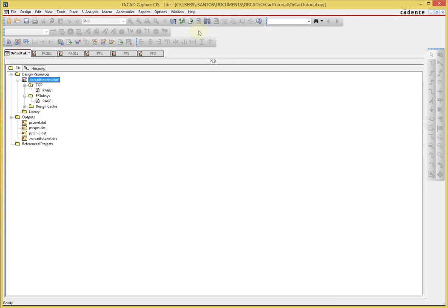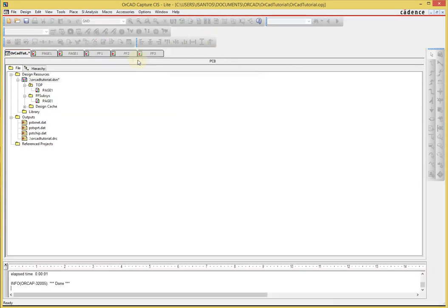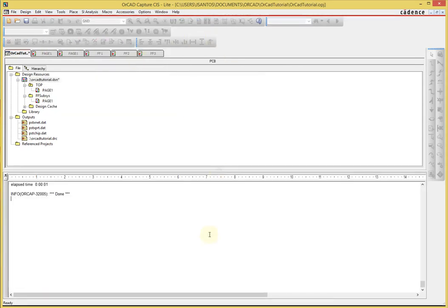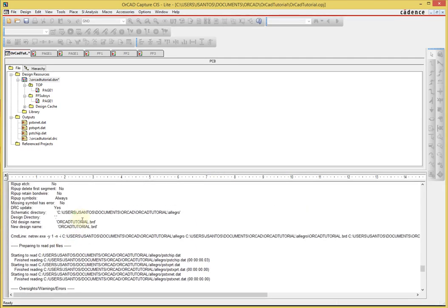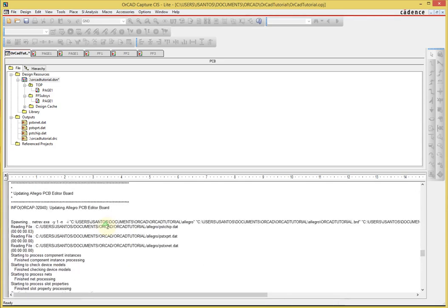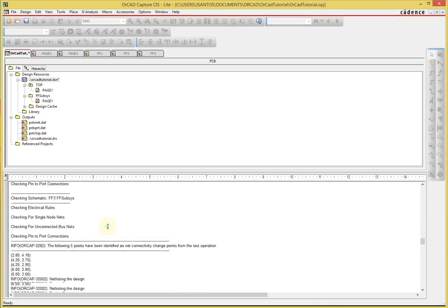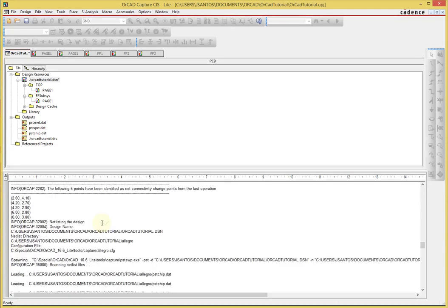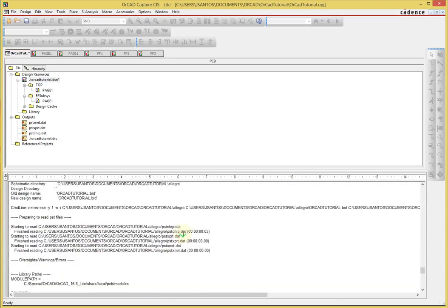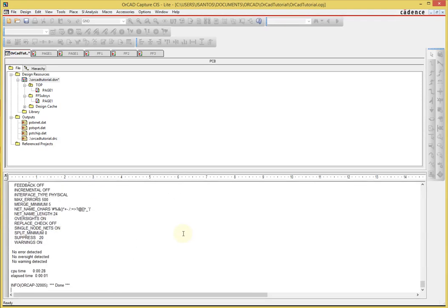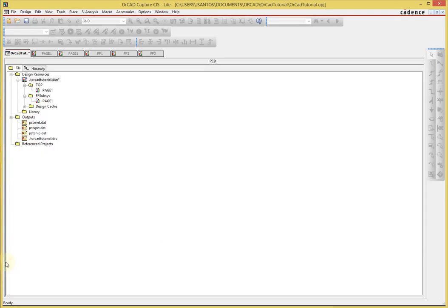And if we have no issues, how do we find out? We need to look at the window session log. Okay, and it's creating the netlist, the board file. Here's when we did the DRC, and here's when we did the netlist generation. If there's an error, first of all, it will fail. You can look at this to see if there's anything that grabs your attention, but it doesn't look like there are any errors. Therefore, the netlist is good. Let's take a look at our folder. Oh, let's save it first. Control S.